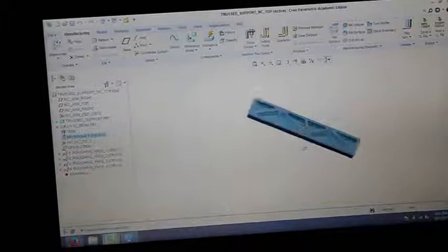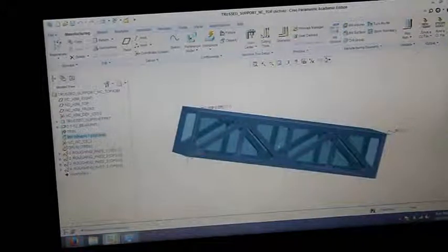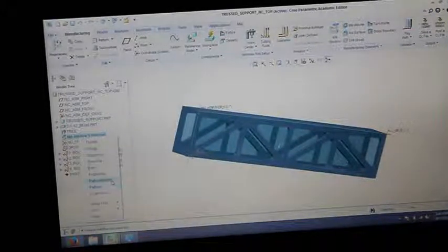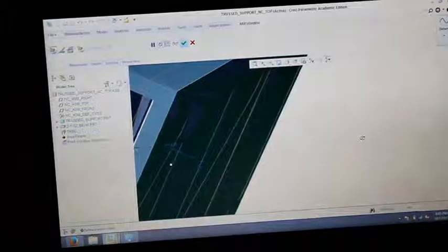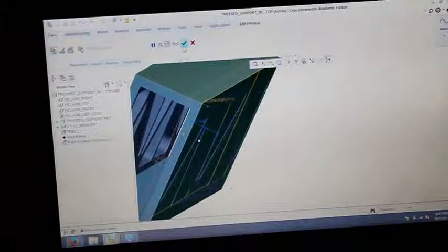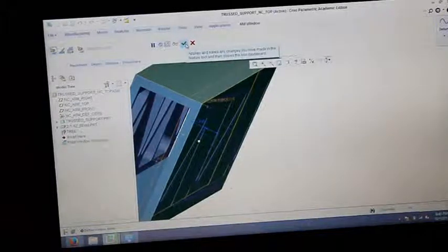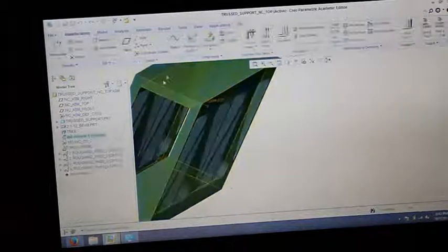The milling window is a fairly straightforward item, and it simply says where the milling bit will travel. It is actually just this plane extruded only slightly more than this face, so as to get maybe a little bit of the scallops that are below this face when we're done with the machining. The milling window could encompass the entire part, or more than the entire part, and it could be of any depth that we want, making it a very flexible tool.